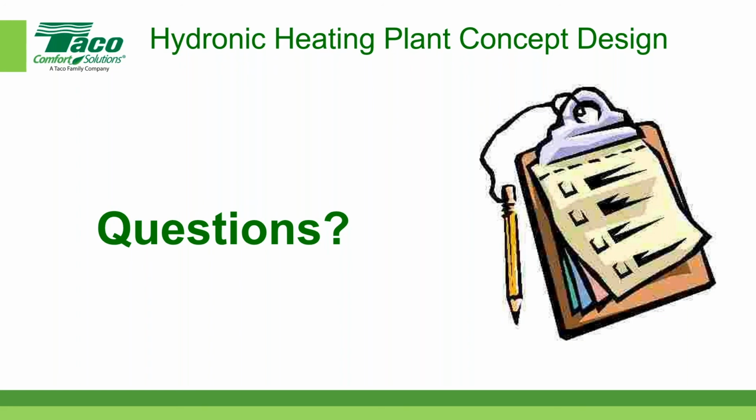Yes, we have a great question from Marissa. Are you supplying the 150-degree water temperature because of Legionella? Did that come into your thought process at all? Well, in general, the temperature for Legionella is around 140 degrees. So I wanted to make sure that my hot water distribution system was greater than 140, which is why I picked 150. And as I said before, with a 30-degree delta T, I knew that I was well within my condensing water range. So that's one of the reasons that I picked that temperature.